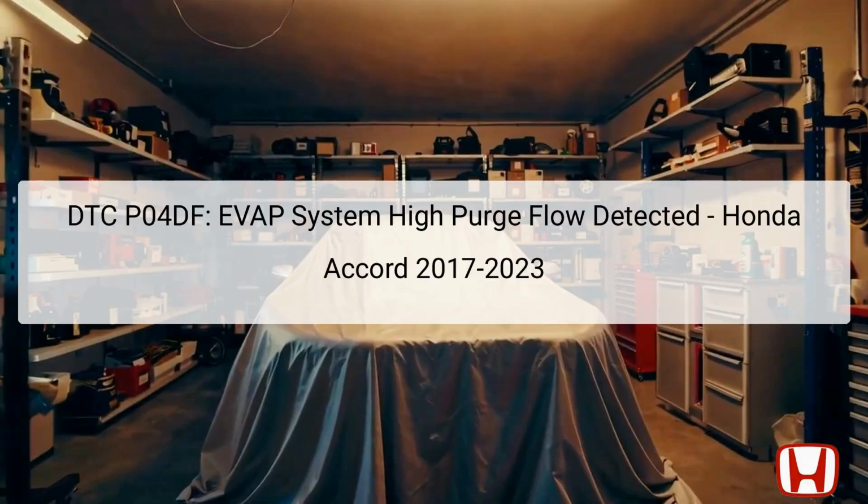The Diagnostic Trouble Code, DTC P04DF, signifies an issue within the evaporative emissions control system, specifically indicating high purge flow. The EVAP system is critical for capturing fuel vapors from the fuel tank and ensuring they are properly routed to the engine to be burned rather than released into the atmosphere. The primary components involved include the EVAP canister purge valve, which regulates these vapors, and the non-return valve that prevents backflow. Faults in these components can lead to inefficiencies and emissions violations.